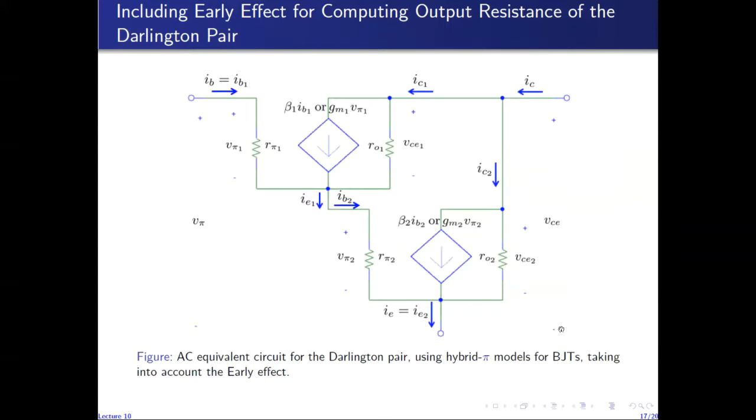And we've already modeled the current amplifier in one of the previous lectures. So we've already derived a two-port model for the current amplifier using H parameters. There we were able to find the output resistance, the resistance looking into the output of the current amplifier, in terms of one of the H parameters, and it was defined by open circuiting the input.